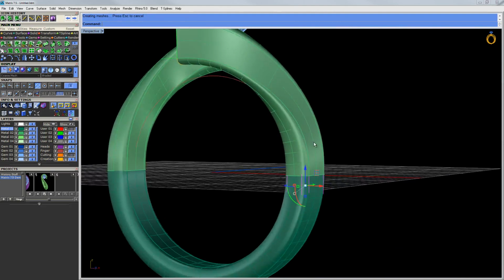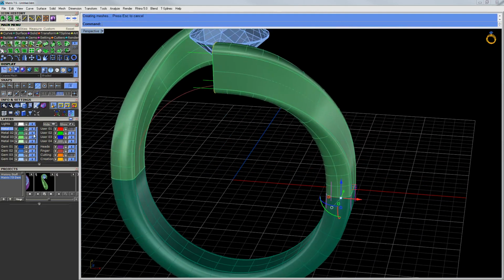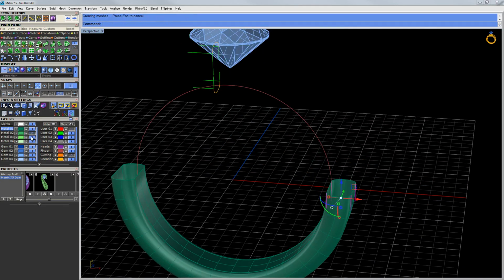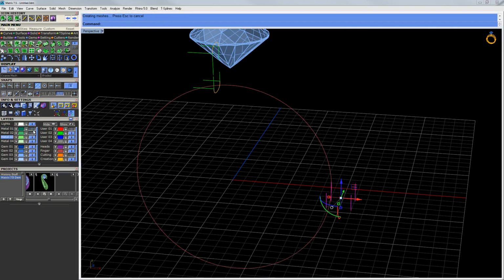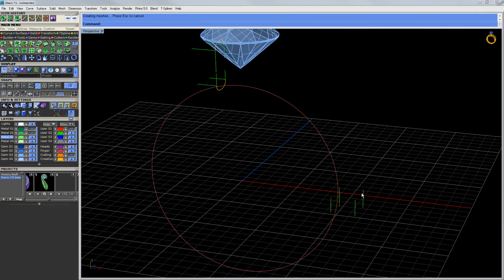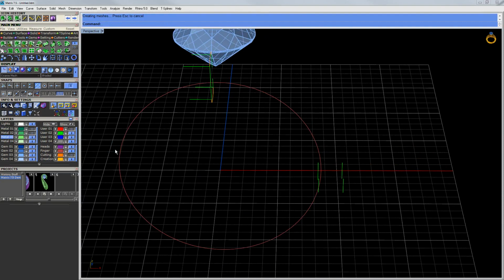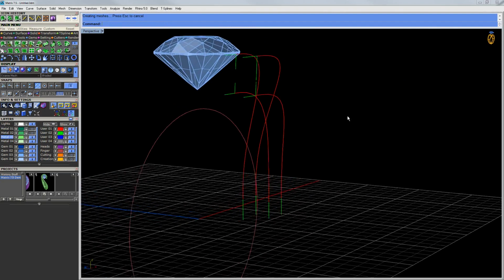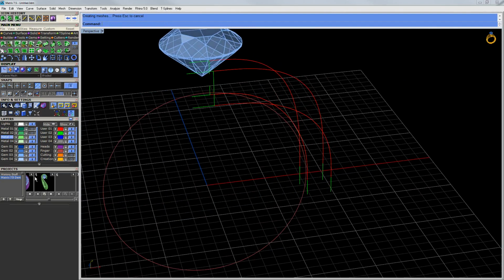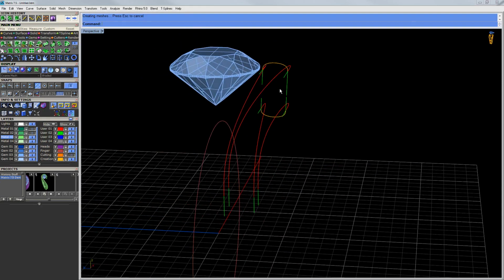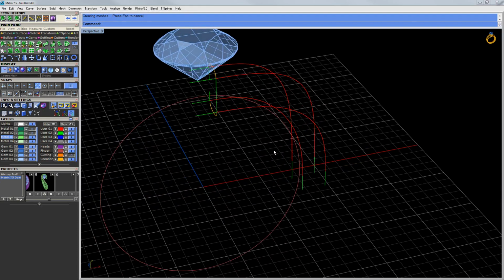If we kind of talk back through how we did all of this, we'll hide some different materials here to make this easier. So these green lines were our originals, and then based off those green lines we created our blends. Alright, not only the rails, but we also created our profile shapes that we use there. So these are all again dependent on these green lines.